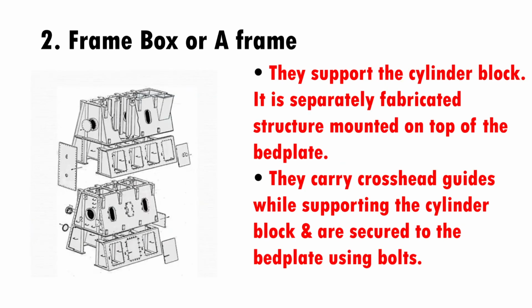A-Frame. They support the cylinder block. It is a separately fabricated structure mounted on top of the bed plate. They carry crosshead guides while supporting the cylinder block, and are secured to the bed plate using bolts.